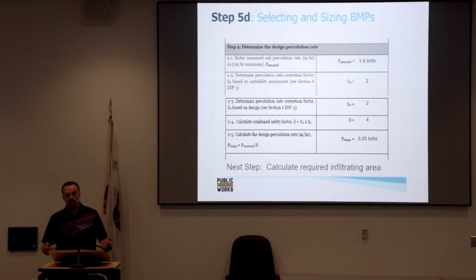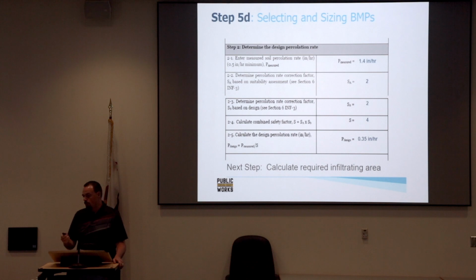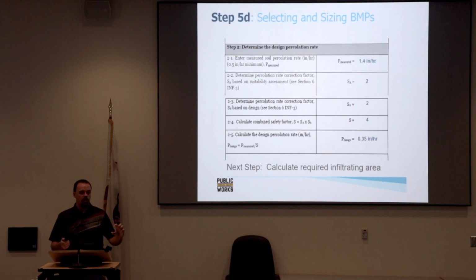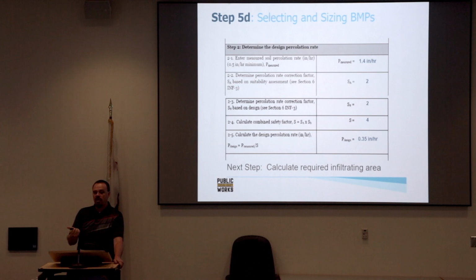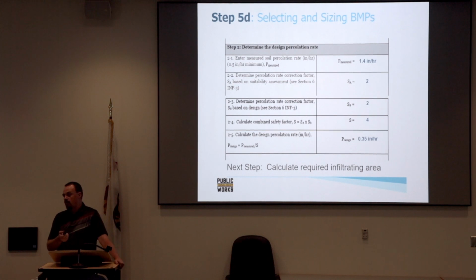If you think of 11 acres of impervious area and you've got to capture 3/4 of an inch across that whole parking lot, that's a lot of water. And the slower your infiltration rate, the bigger your BMP needs to be. So it just makes that much more sense to do solid geotechnical investigations ahead of time to make sure, because in this case, for example, at the government center with the dry wells, if we would have gone by the web soil survey, we could have used like 0.8 as the KSAT value.